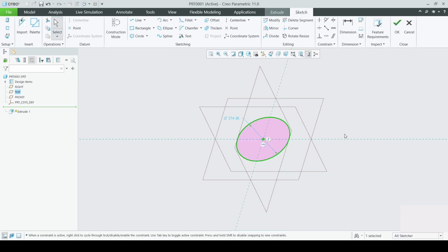Okay. And we will double click it and we can write here dia, because this is the diameter of the circle. So we can write that driving parameter of dia here and press enter.